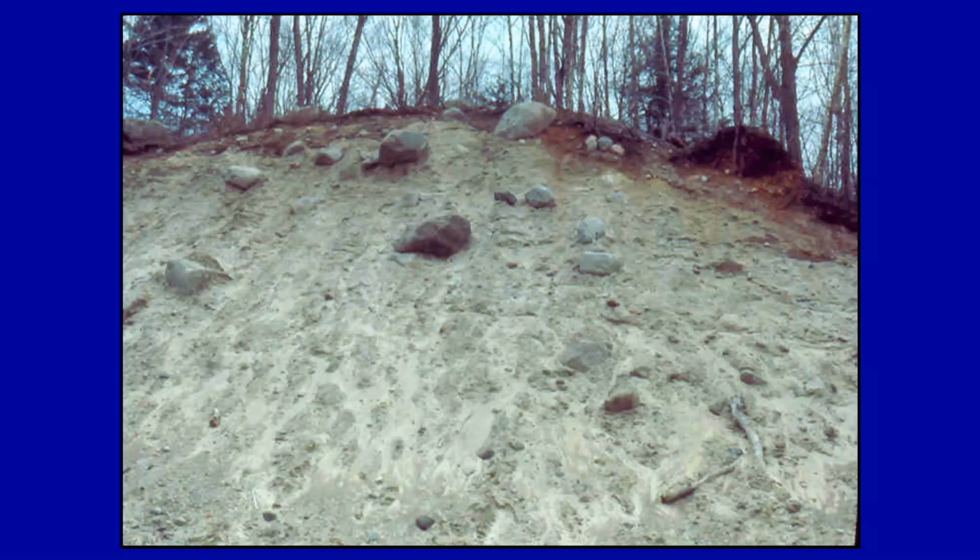However, if we are talking about something that is laid down as the glacier has thousands of feet of ice on top of it, it is much denser. And this becomes somewhat important because in the development of bedrock wells, in many cases, it is overlain by glacial till. If you have an ablation till, more water can be stored within it and it can dewater into the underlying bedrock fractures more effectively.